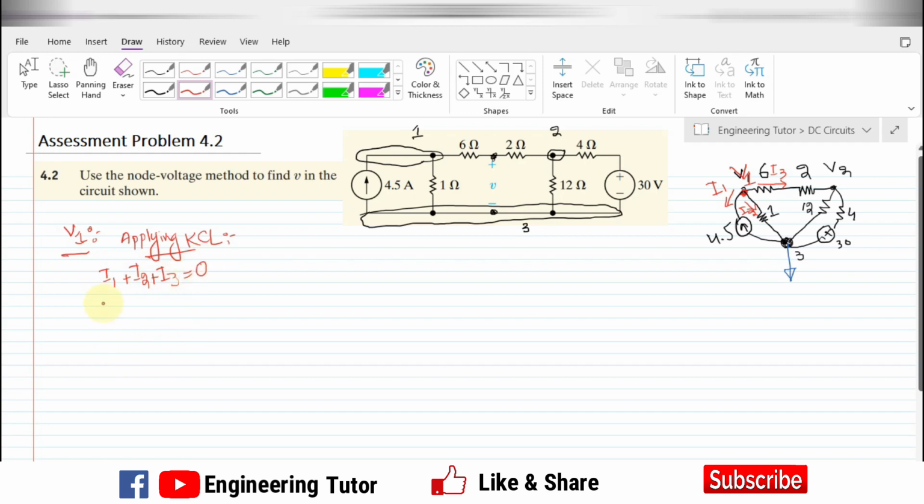We know that the value of I1 here is 4.5, but the direction of this current is opposite to that of the current which we have supposed. So this current is minus 4.5. Similarly, the value of I2 is the potential difference divided by the resistance, which we find by using Kirchhoff's voltage law, or KVL.